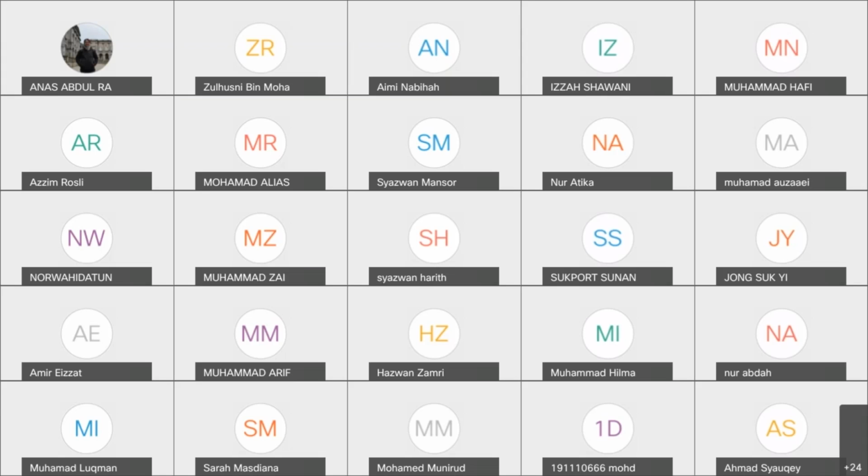But if you ask me, it depends. For example, in Thermo 1, when we want to check the location or state, whether it is in the compressed liquid, saturated mixture region or superheated region, it's easier to look in terms of temperature. So we go to the pressure table, and at that pressure we look at what T sat is. If the given T is lower than T sat, the saturation temperature, then our state is in the compressed liquid region. If it is higher than T sat, it means it is in the superheated region. So I think it depends on your understanding. There is no priority.